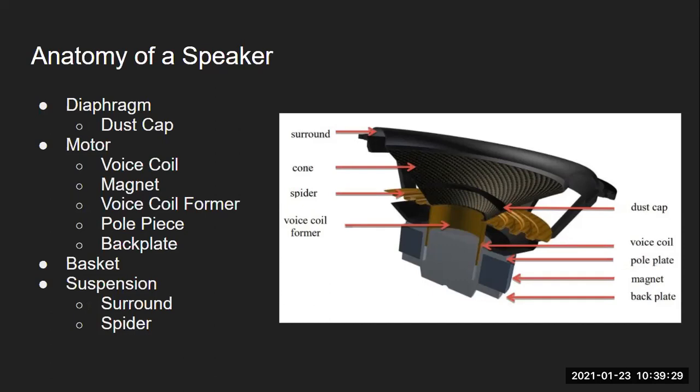It's a stiffer component, and it's acting as a restorative force in this spring mass damper system. When you've stopped playing an electrical signal, the speaker will want to mechanically revert back to x equals 0 at rest. That's also what's going to control the general damping factor, which is defined as a Q number. That's a major component, as well as the overall weight of the system.